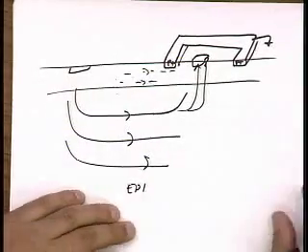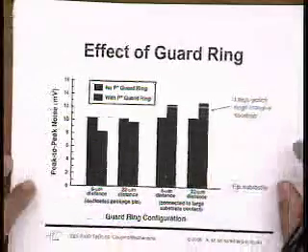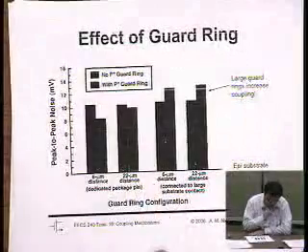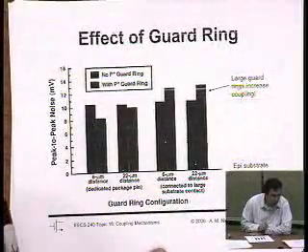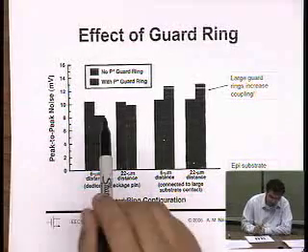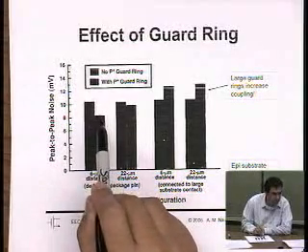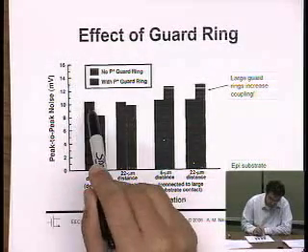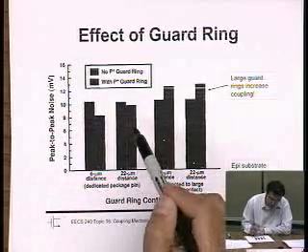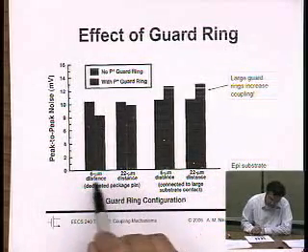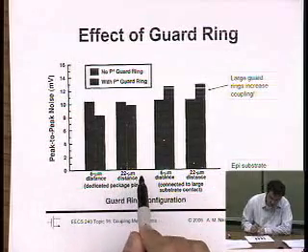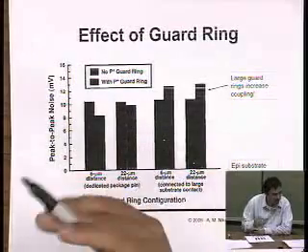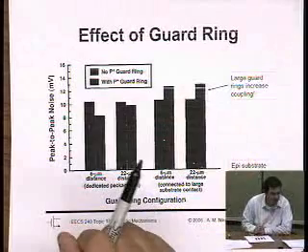And in fact, you can see it in measurements and in simulations. Again, this is, I believe, from the same paper, so this is the peak-to-peak noise voltage pickup with and without the guard ring. And of course, it's hard to tell which is which. But let's assume that the one that's smaller is with the guard ring. So okay, things are getting better, but hey, not much better. I will go from 8 millivolts to 10 millivolts to 8 in this case. But this is for close coupling. If I go to far distance, then actually it makes no difference. Almost the same voltage. And that kind of jives with our understanding that for far distances the current is mostly flowing in the body.